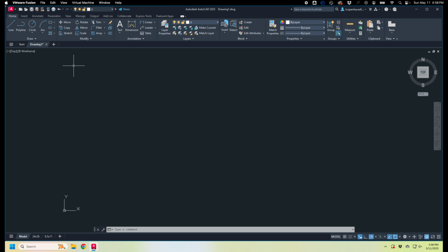When you're navigating in AutoCAD to start with, it's useful to have something to look at and to reference. So let's do that by just giving ourselves a rectangle. I'm going to come up to the ribbon up here at the top. That's what this is. So go to the ribbon and then go to the draw panel, which is the first one. I'm going to click on this rectangle button.